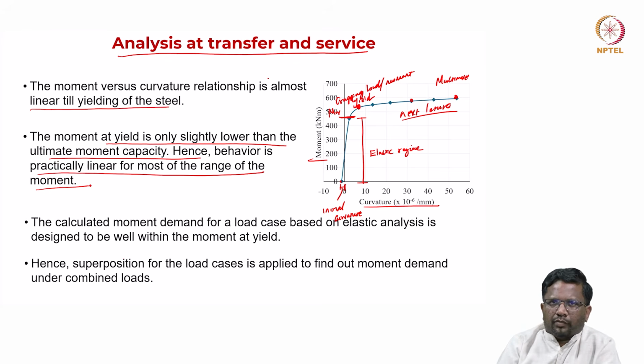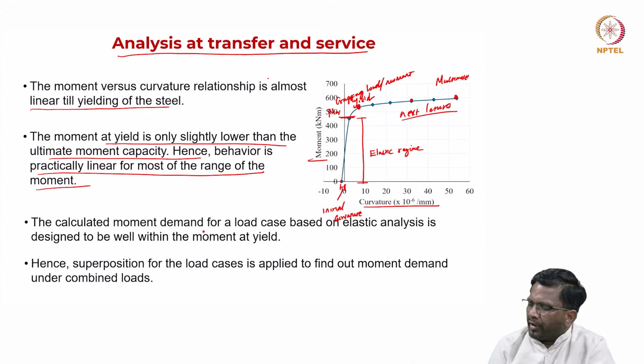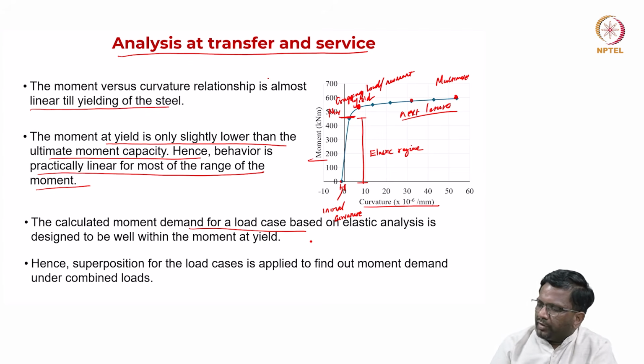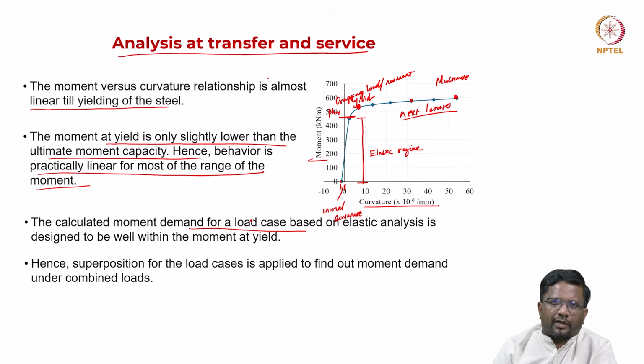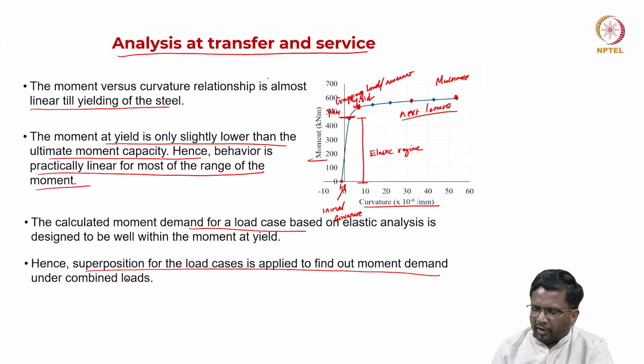So if the calculated moment for a particular load on the beam is based on the elastic analysis, we make sure that the moment demand when we design it is in such a way that it is going to be less than the cracking load, or we will make sure that the pre-stress concrete sections are not going to be cracked under service loads. So, the superposition of the load cases is applied to find out the moment demand under combined loads.